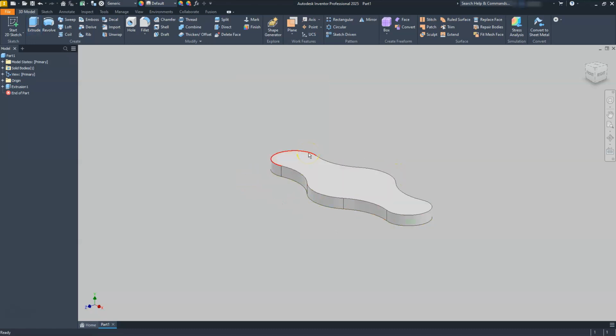Next, I want to decide where I'm going to place these next circles at, right? I can either do it on the top or on the bottom, and that all depends on how you want to do your calculation. So I brought this up when we were doing AutoCAD 3D, is that if I want to start my cylinder here from the bottom and go up, then I can use the numbers that are directly on the drawing. If not, I'll have to do the math of it and subtract 20 from whatever number those are. So I'll just do the subtraction on this one.